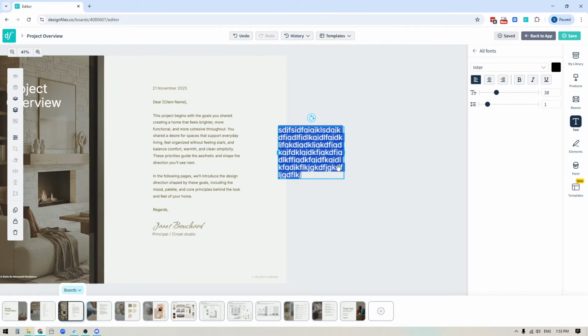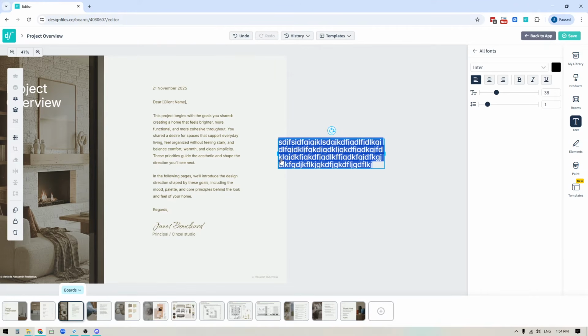Now, the other thing that we have done here is that with this particular text block, and I'm just going to make this left aligned for now, originally when you were expanding your text block out to the side, it was actually expanding it from the center out and expanding to both sides, which wasn't ideal because if you were trying to left align everything, then having it expand from both sides made it really difficult for you to get the placement exactly right. So we fixed that problem, and now if I choose to expand it from the right, it's never going to affect the left-hand side. Additionally, the same thing goes for expanding to the left. You'll see that this has never been altered. So it helps you keep the alignment of your text in place as you are building out your templates or just adding whatever notes that you want to add to your design boards.